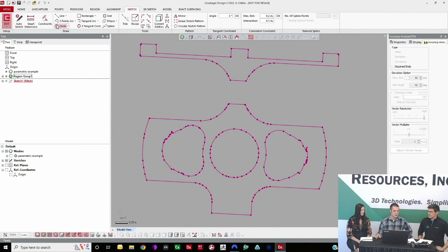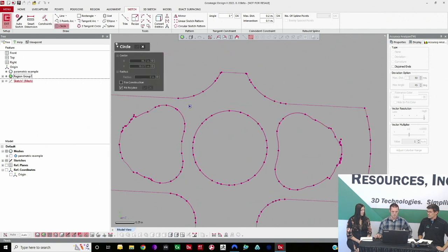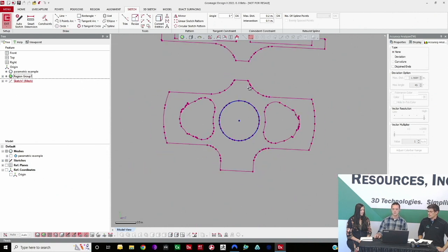And I'm going to grab my circle tool, and I will just marquee select around this circular area in the center. And you'll see that Design X, once I have that selection performed, will automatically best fit a circle to that preview image. The circle has some characteristics here. You can see its radius is 0.4887. It has a position which is inconsequential to us at this point since the part's floating randomly in space. But once I get this part aligned, this will be XY 0 because this will be the origin of the part. So go ahead and hit the checkbox on this.